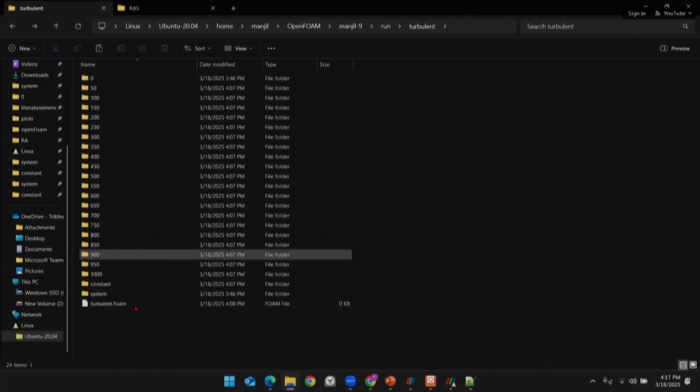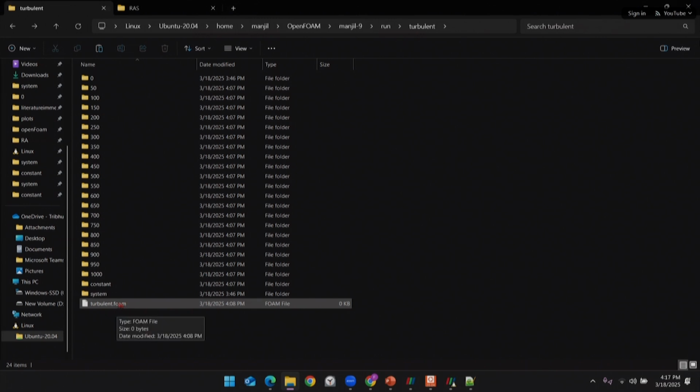Okay, what is the foam file that you have created? I think the foam file is wrong. Turbulent.foam, with the capital letters and all those. Have you checked that? Yeah, I have created the result file as touch result.foam. So you have used result in all small letters in the foam file. F is capital. F is capital. No, okay, that's the problem. So just make it small. Okay. Thank you. Yeah, I can see my simulation didn't run, but my controlDict steps are as you have shown.